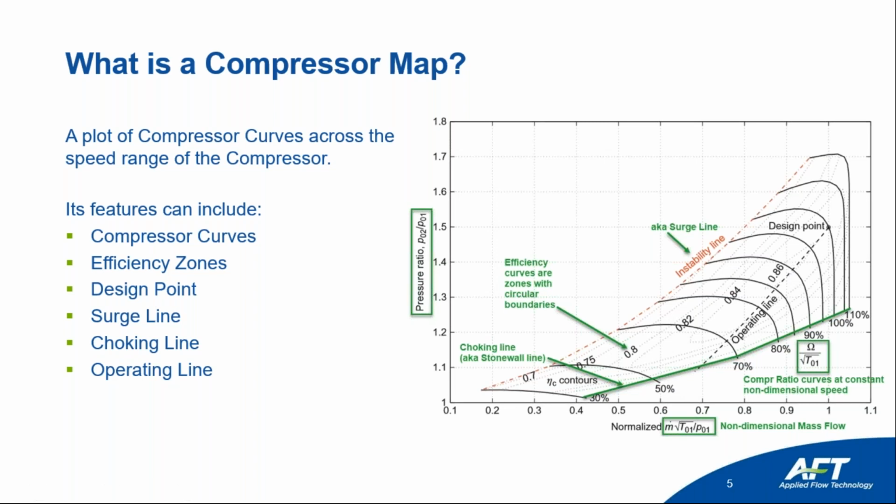Compressors are very dependent on their inlet conditions for operation. So what these normalized or non-dimensionalized units attempt to do is allow manufacturers to give out curves that can be used for fluids other than what the testing fluid was at different operating conditions. So in this case, the RPMs in a compressor map normally can be found in the non-dimensionalized form, as well as the flow.